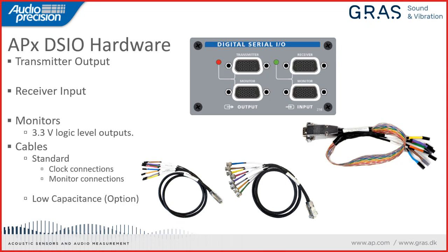But as the data rate has gone up, the fact that the probes add resistance and capacitance may themselves impair the connection. So on the digital serial I/O module, we actually provide electrically buffered connections that are snooping on the interface signals, but are not electrically loading it and can be connected directly to an oscilloscope.